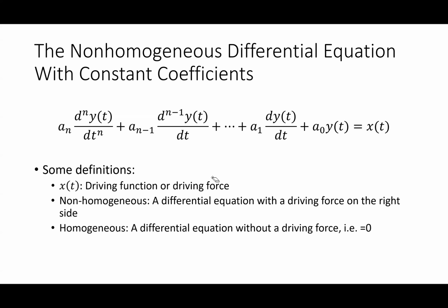So if we say they're constant, we mean the coefficients basically are just numbers. Could be complex numbers, and we'll see that. There's a lot of systems where they are complex numbers. This thing over here is what I call the driving function or the input. It should always be the case that if you guys are doing a circuit like in 2112, the input source, whatever the voltage source or current source, better end up on one side of the equal sign. That's always going to be the case for your problems.